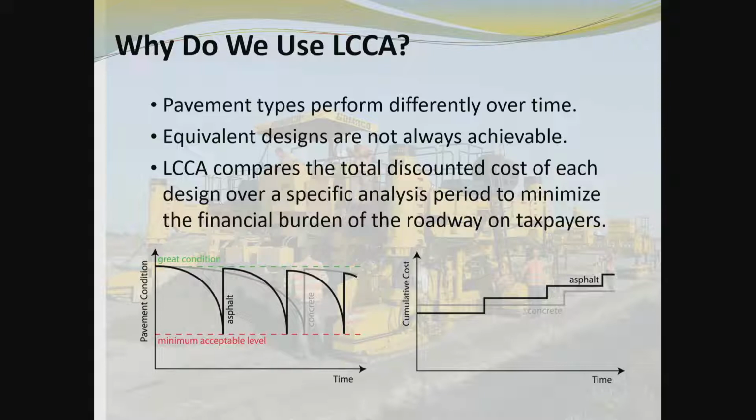The difference becomes more and more profound the heavier volume of traffic that you have. So for us, let's say for an interstate highway in a rural area, that difference might be 10%, might be 15%, because the volume of traffic is relatively low, and if you consider user cost, it's a big input.